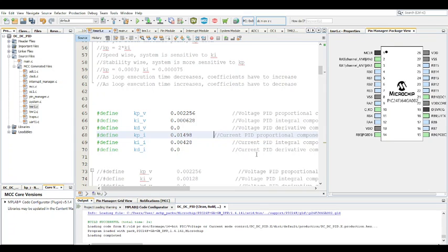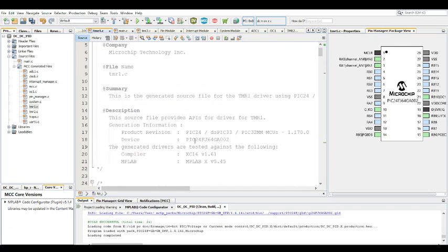Not to give an object human qualities, but there's like a narrow range where they actually work properly, help your system, and then right after that they just cause all kinds of problems, like the system reaching the set point and all of a sudden oscillating, just randomly oscillating. That's what the Kd does. And anyway, that's the entire system.